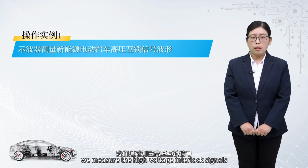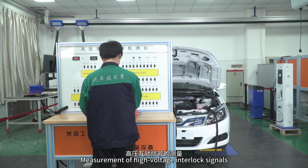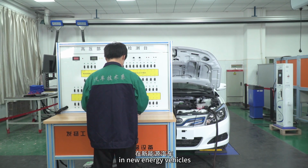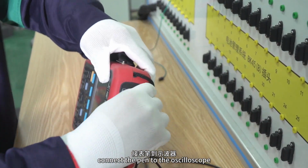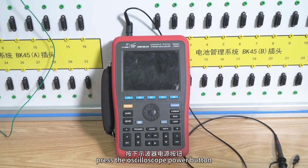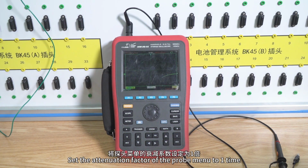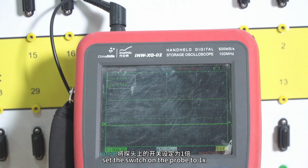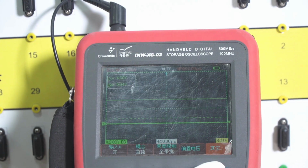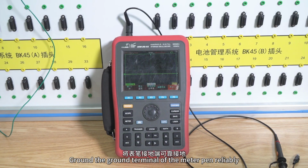Next, we measure the high voltage interlock signals to get a feel for the basic measurements. Measurement of high voltage interlock signals in new energy vehicles. First, connect the pen to the oscilloscope. Second, press the oscilloscope power button. Third, set the attenuation factor of the probe menu to 1 time. Fourth, set the switch on the probe to 1 times. Fifth, ground the ground terminal of the meter pen reliably.